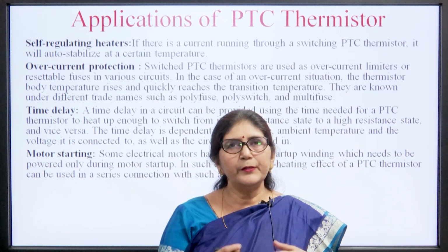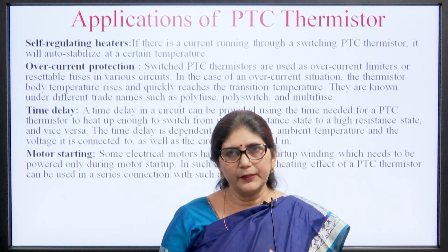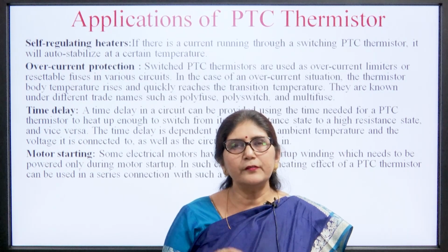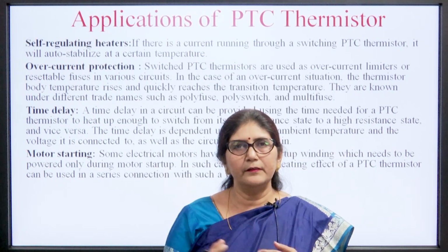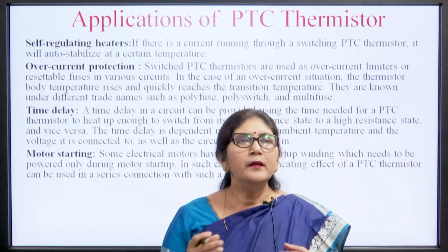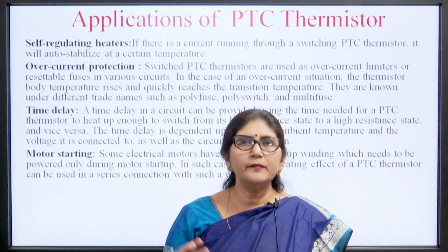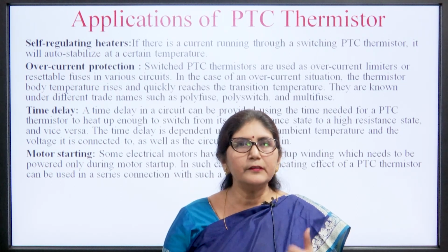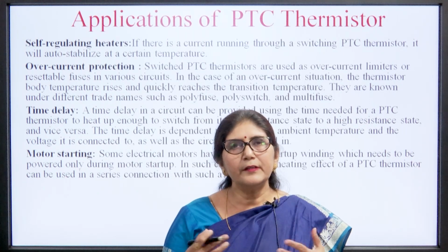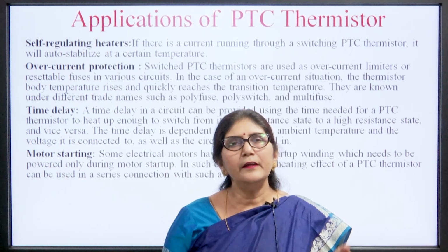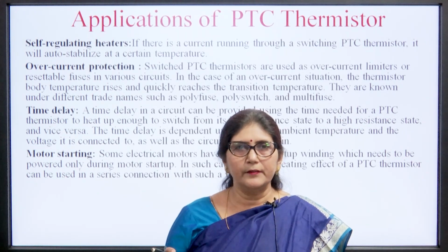But after a certain period of time, the PTC thermistor will get self heated and its resistance increases, and because of the increase of resistance the current will decrease, and after a certain time when resistance is very high, no current will flow through that circuit.